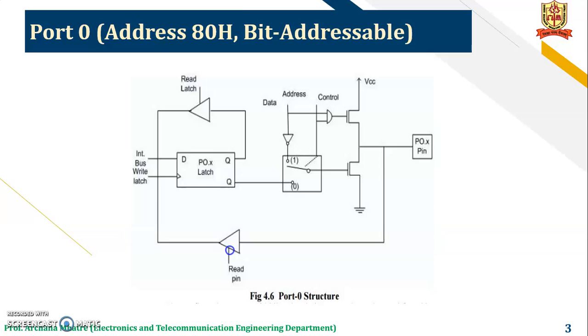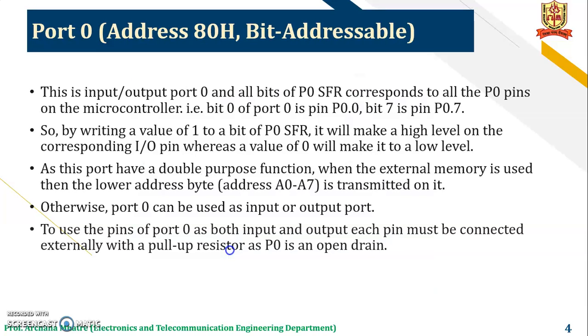Port 0 has the address 80H in the internal RAM, and it is a bit addressable port. It is an 8-bit port. Now, this is the internal structure of port 0. This is the input-output port 0, and all bits of port 0 SFR correspond to the P0 pins on the microcontroller.